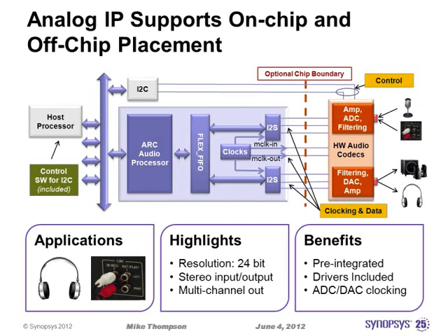On the other side, we have an AHB or AXI bus where you can plug in the host processor, and we're host agnostic here. We don't really care what host you use. Now, we'd prefer you use an ARC core host, but if you want to use ARM or MIPS or Intel x86, that's fine too. We interface quite well to all of them. And then also that AMBA bus gives you access to all the interface IP, HDMI, MIPI, whatever else you're running in your system.